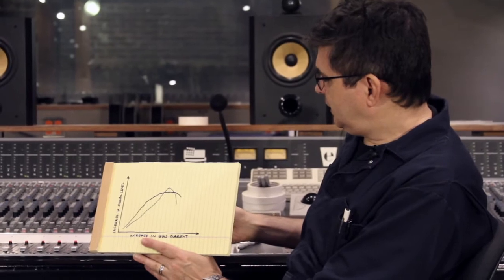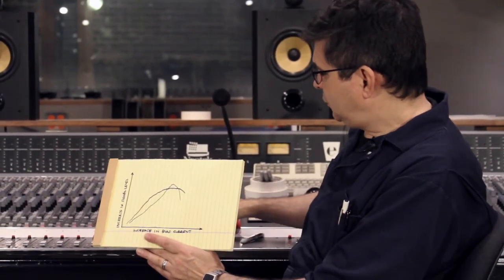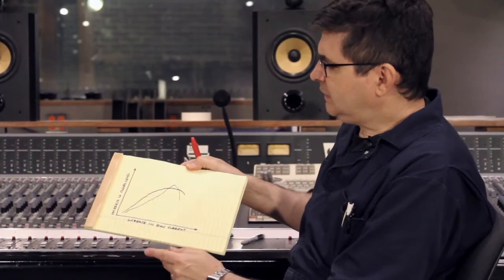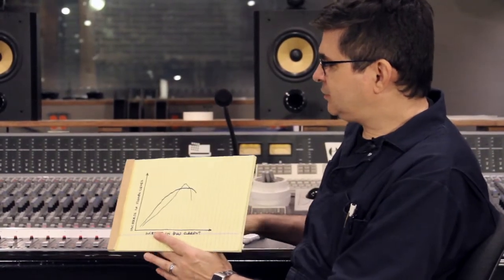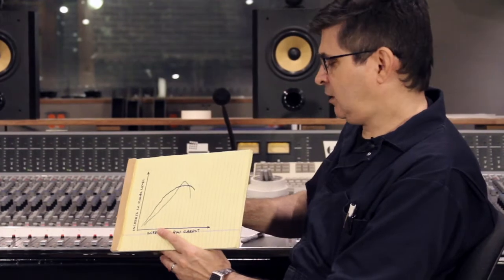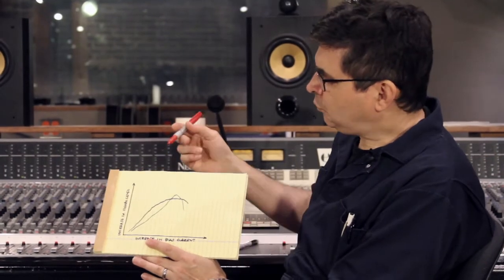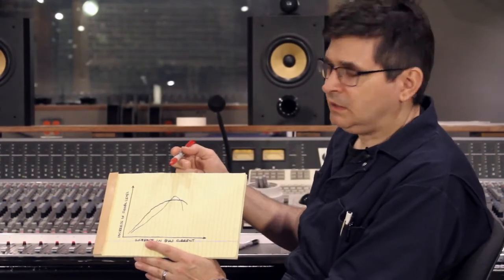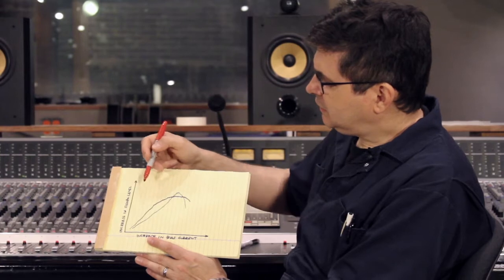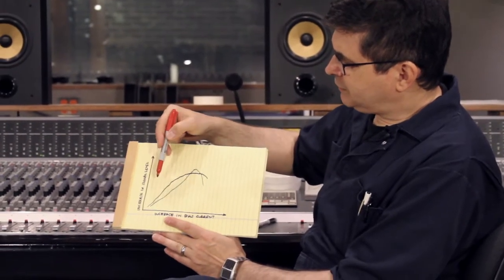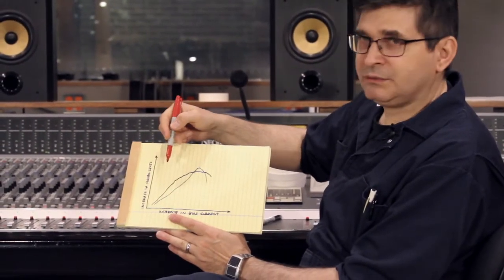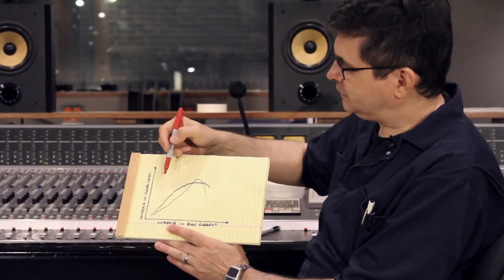And now, a third characteristic would be the noise performance of the machine. That is, the distortion component, the second harmonic and other distortions, and the background noise of the tape, relative to the signal level, are also affected by bias. So if we start from a position of no bias, there's relatively little signal and relatively high noise.